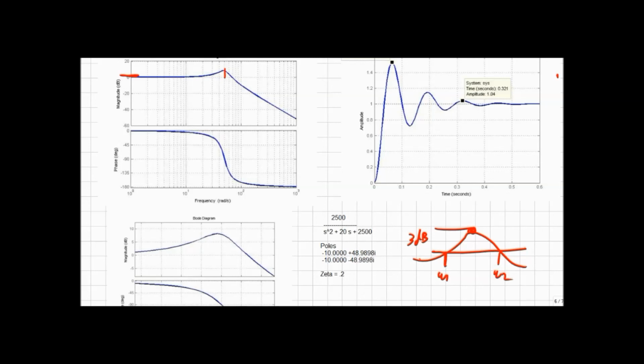I don't have to worry about omega n or anything; I'm just looking for those. Then I have my equation: zeta equals omega 2 minus omega 1 all over omega n. I guess I do have to worry about omega n there, but omega n is going to be somewhere over here in this thing.